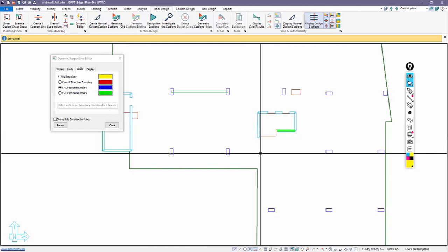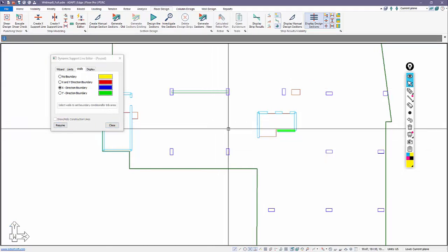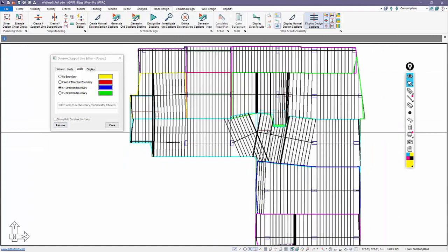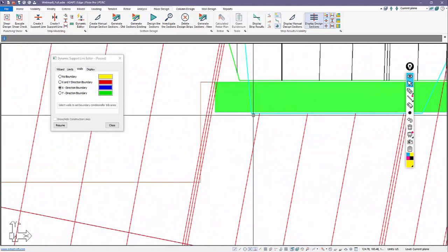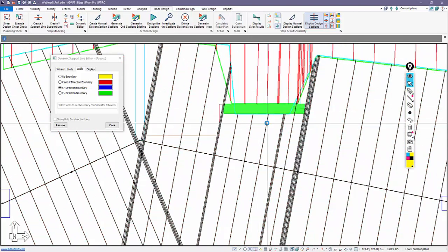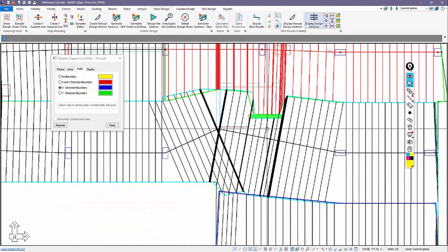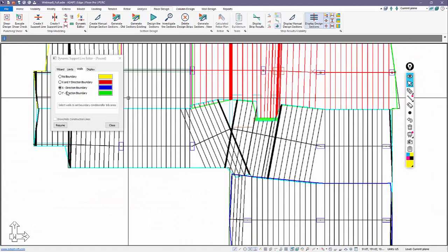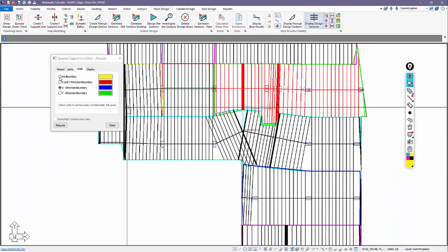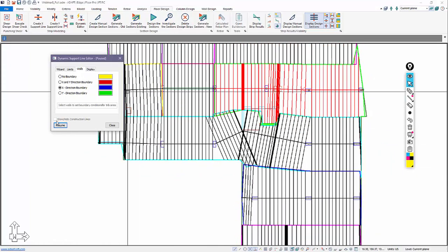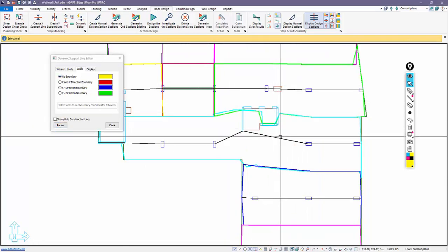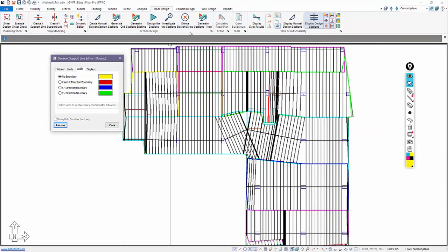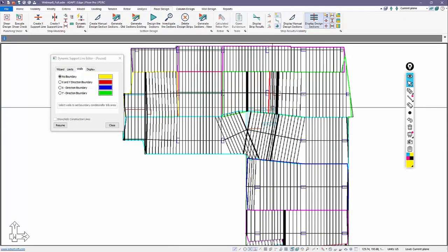But if we go ahead and pause this again and we generate the strips, now you can see the program truncates this cut and it actually extends it just off the face of that wall. Same thing on the other side, so the program doesn't cut into the wall. And you can use these wall options to be recognized as boundaries or no boundaries. If I go back and I say no boundary, in this case, I'll set this back to no boundary and then regenerate. Let's pause that. You can see it crosses through the wall again.